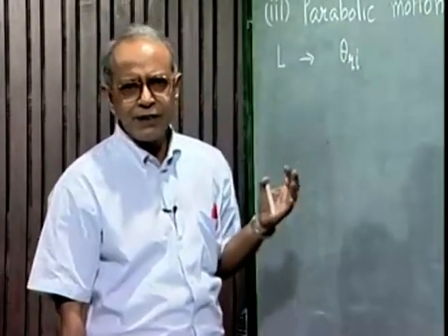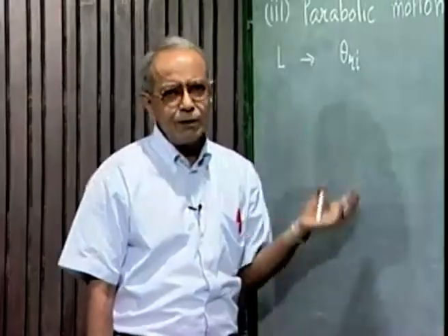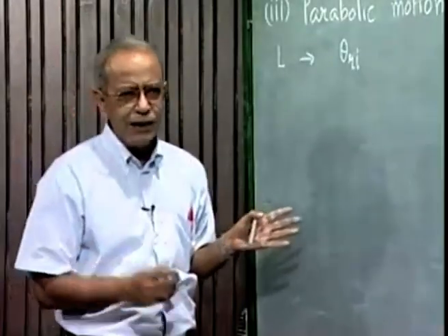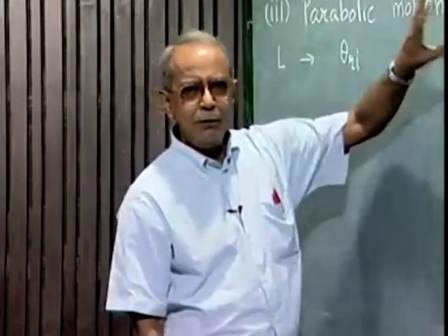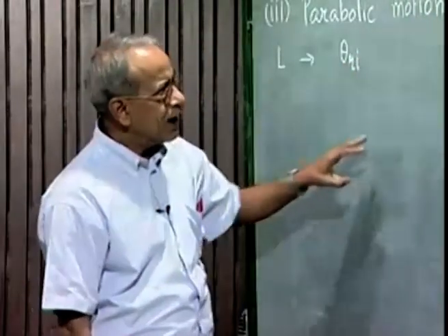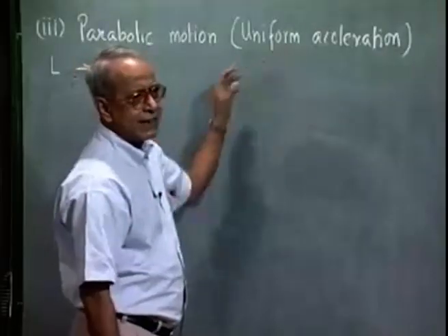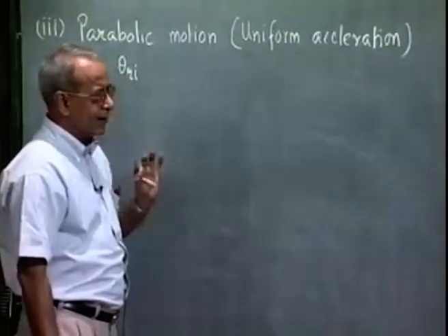Any other variation of acceleration will make the maximum value of the acceleration during the cycle more. So, the maximum value of the acceleration will be minimum if it moves first half with constant acceleration and the second half with constant deceleration.